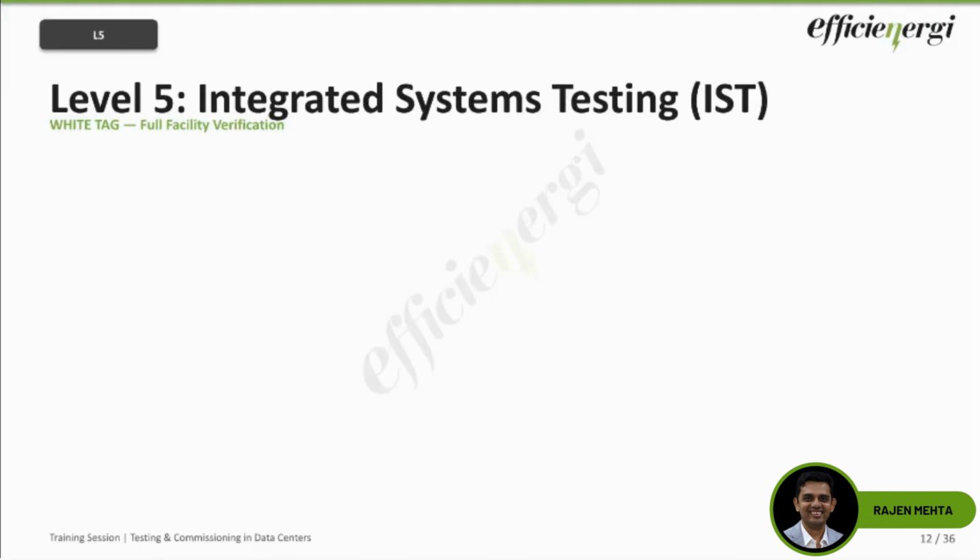Now, IST is in a lot of ways the ultimate test, I would say. It's the ultimate test of the entire facility. This is where we are going to prove that the entire data center can survive a real world failure scenario. If you claim, for example, an N+1 redundancy, then whether or not it is really an N+1 redundancy, IST is the time when you are going to prove it.